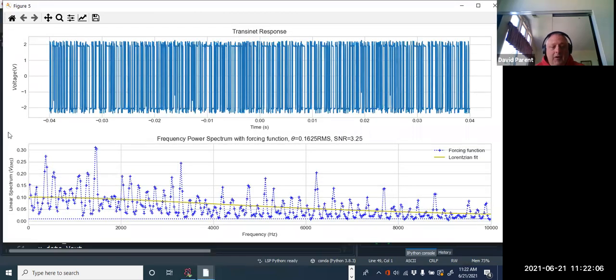Okay. So all this is just noise at each frequency bouncing around, right? But I'm extracting a Cauchy curve to it, so that I will always measure the signal to noise ratio based on this curve here, this point. I'll take the peak and its relationship to the curve.